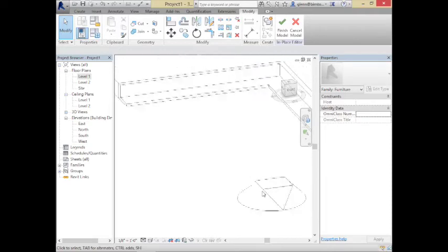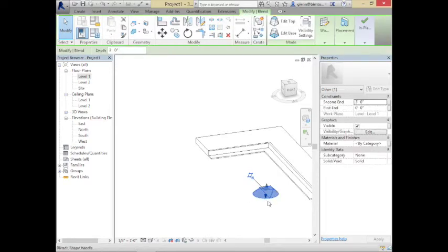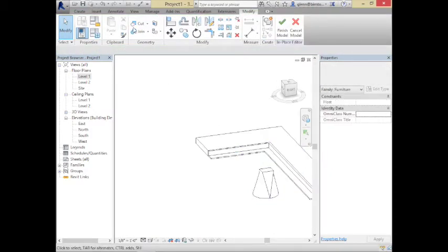So just like I explained, do you see how we have a bottom section that was circular, and then the top is rectangular? So you could do anything you want, and while you're here, you could always edit the form of the blend you just created. It's conic on two sides and then flat on the other two sides.